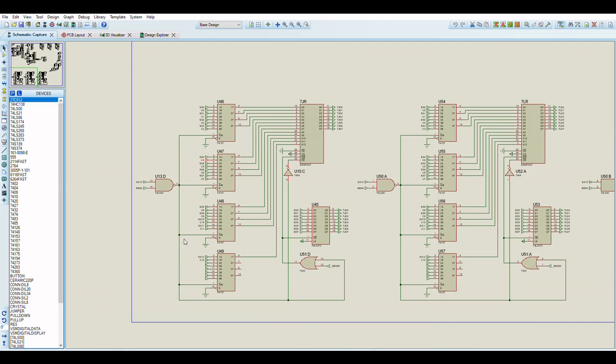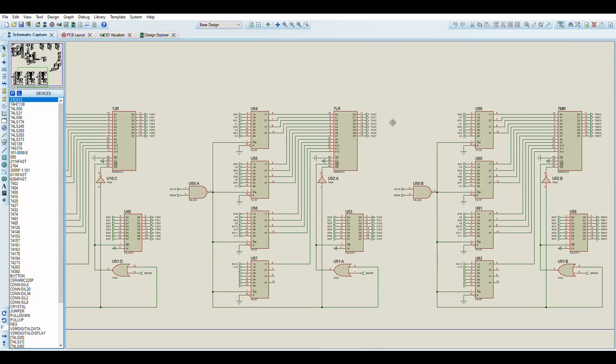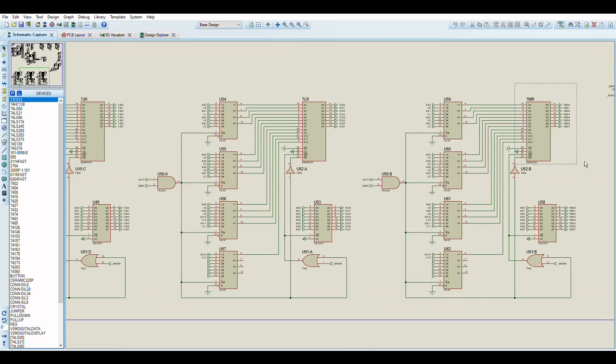So the sprite definition index, which was also read from the sprite data, just forms the upper bits of the total address being used for the sprite bit plane memory. So it's a really efficient way of decoding the sprite data that you want to read from memory.